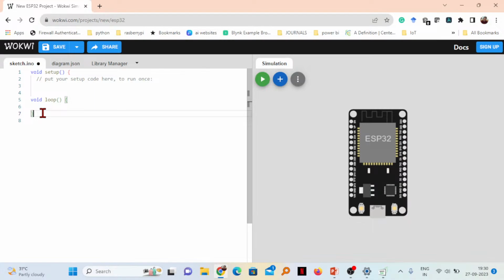So in this particular program, we are going to write a program that can switch on and switch off the internal LED of the ESP32, and then we will see how we can use the other pins as well. So here we have to write pinMode. If you write pinMode, the inbuilt function automatically pops up here. The actual spelling is PIN and the M should be capital here.